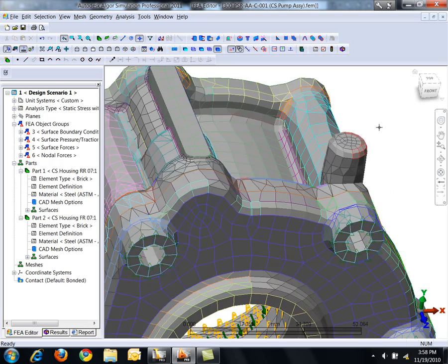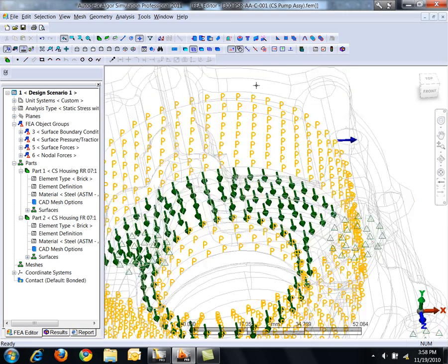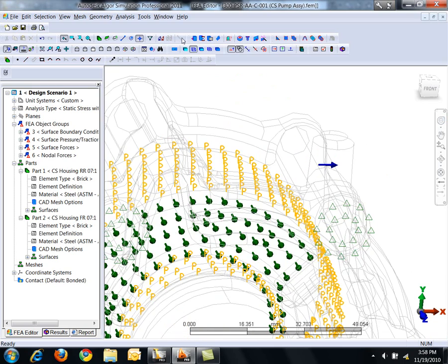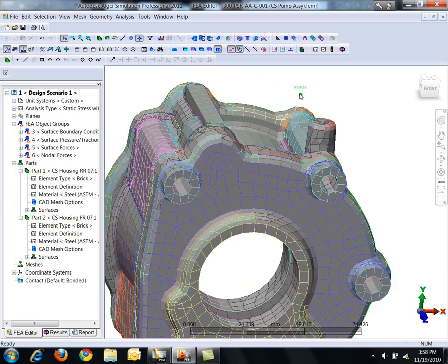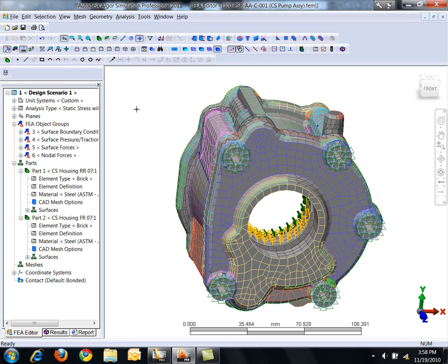What that does, if I take a look at my internal geometry here, we have a load just on that one point in particular. So these are some very commonly used options, but the most important part here is to recognize that to add loads and constraints, all you have to do is select a surface or a point or whatever you would like to load, right click, go to Add, and then select your load or boundary condition.